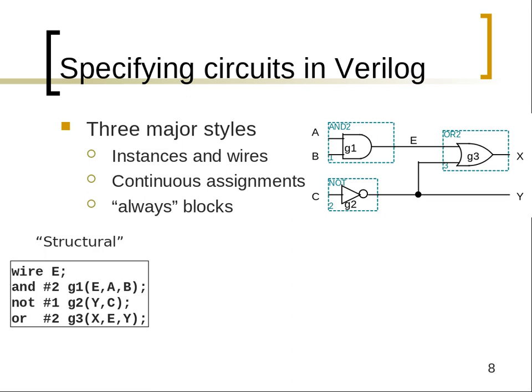There are three inputs in this diagram, A, B, C. There are two outputs, X and Y. All right. C first goes to a NOT and then is piped directly to Y, and then is also piped to the input of gate 3. And we're going to call gate 2 a NOT, or G2. G1, gate 1 takes the two inputs of A and B, produces an output. We'll call that wire E, because we have to label what this wire is, and then we'll pipe that over to G3.